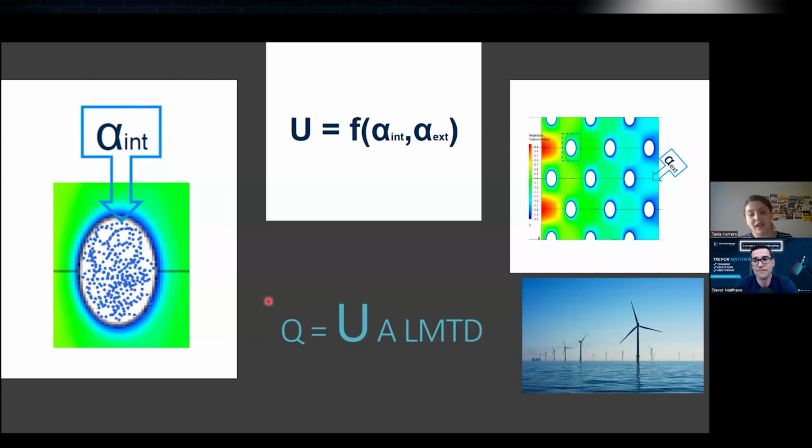But I mean, it's something that we have to deal with, and it's very important to consider. Yeah. Also, if we are talking about the evaporator, for instance, if we have smoking rooms, the chemicals that the industry uses for this kind of application are corrosive with some metals, and that's why we need to consider stainless steel or special coatings in order to avoid that.